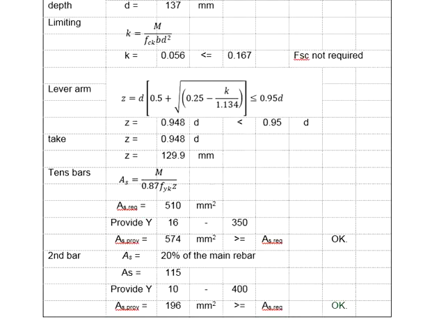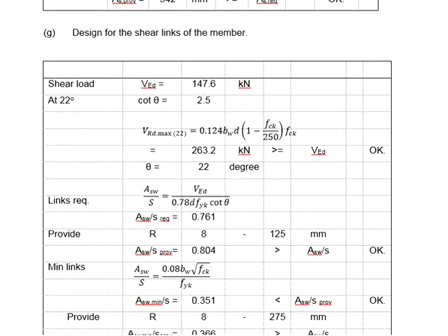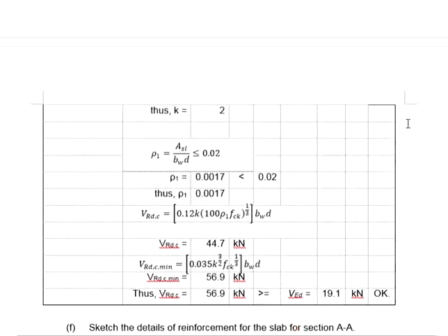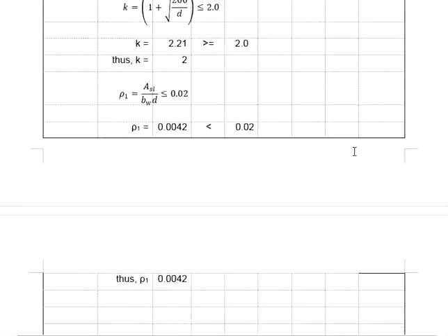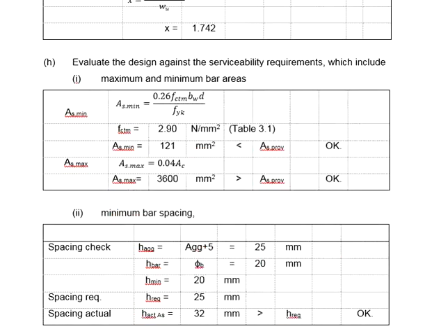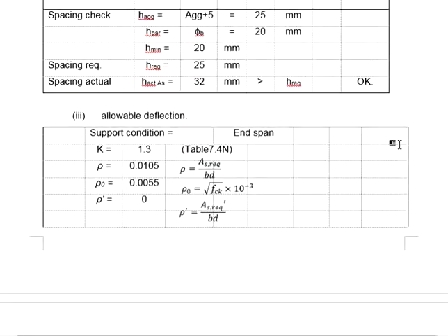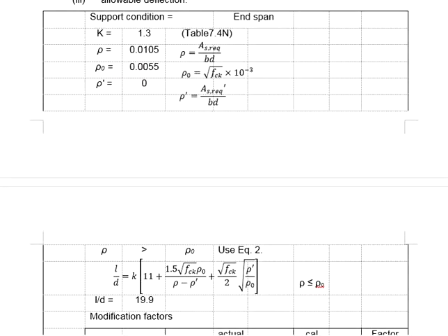in the staircase. You also notice that even though all the structural members require the design for the shear reinforcement, however, the equation set used in the beam differs from those used in the slab and also the staircase. Not only that, for the serviceability requirement, some are checked in the beam but not checked in the slab and the staircase.